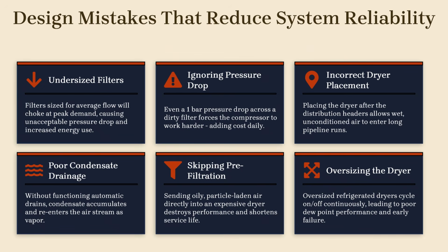Many compressed air systems lose performance because of avoidable design and maintenance mistakes. One common issue is undersized filters. During peak airflow demand, these filters create excessive pressure drop, forcing compressors to consume more energy just to maintain pressure. Ignoring pressure drop across dirty filters can silently increase operating costs every single day.